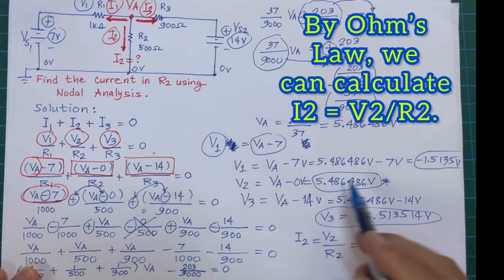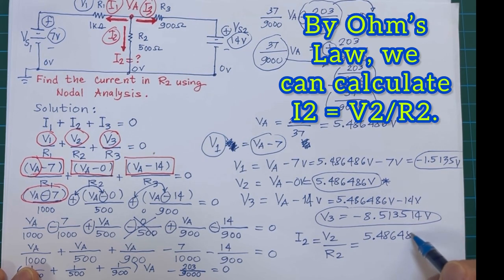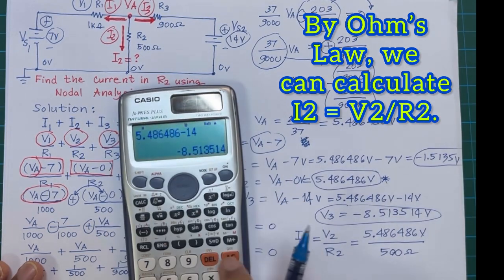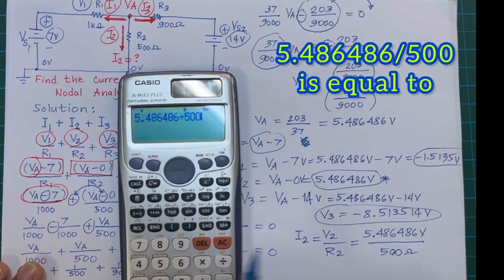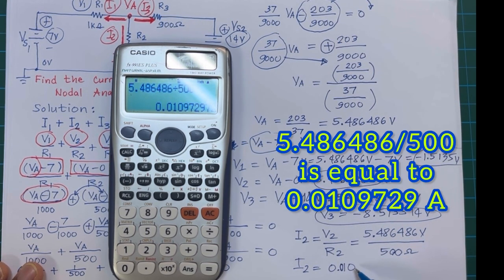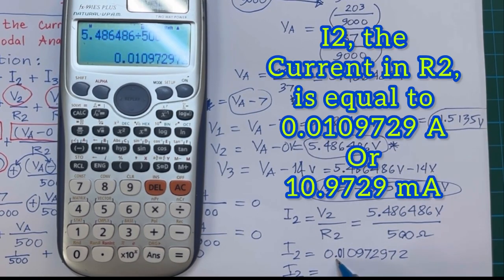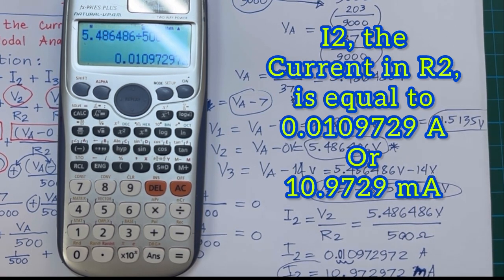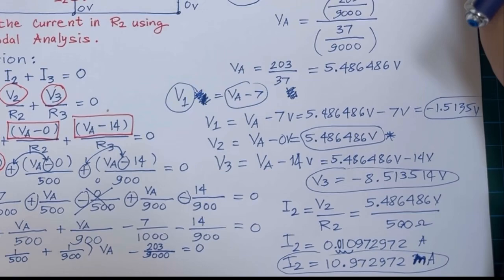I2 only will be calculated over here, and by Ohm's law, we get V2 over R2, and the final answer, of course, will be in amperes, because it's volts divided by ohms, but we may change it to milliamperes also. So we got 0.0109729 amperes, or we can make it short like 10.973 if we want 3 decimal places on the fractional part.